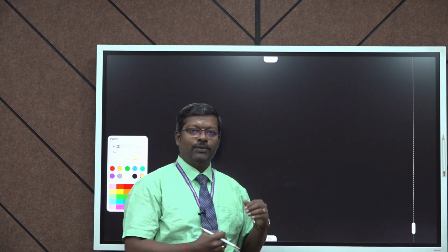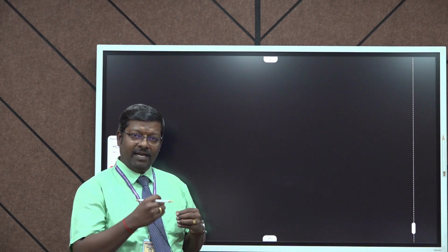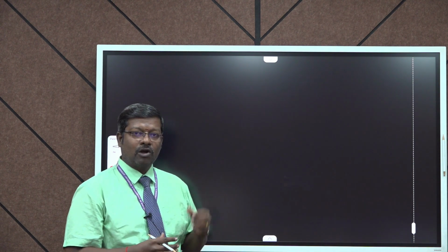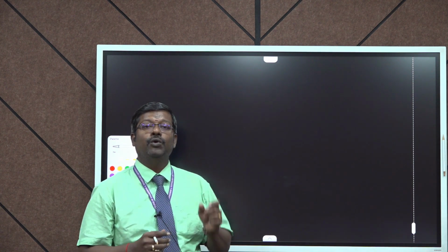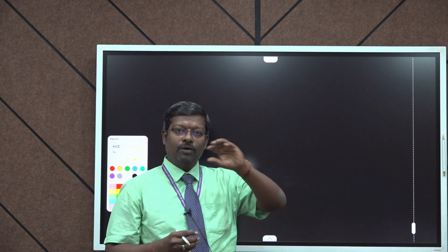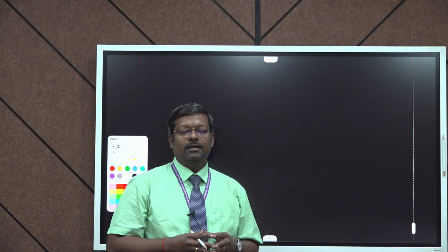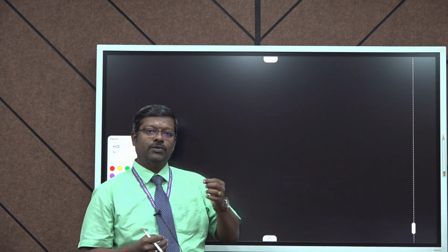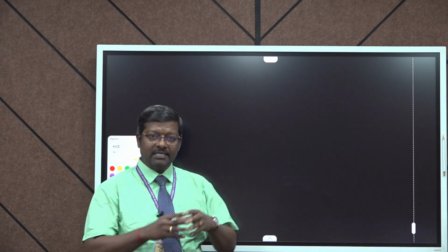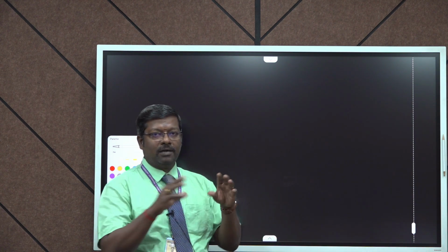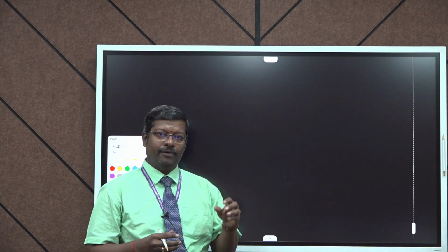Before going to Euler's column theory, initially we need to know the assumptions first. The first assumption is the column is initially straight and of uniform lateral dimension. Then the column is made up of a homogeneous and isotropic material, and the load acting on the column is perfectly axial and the load passes through the centroid of the column. These are the most important assumptions in Euler's column theory. Based upon these assumptions, Euler has derived 4 derivations for different end conditions of the column.